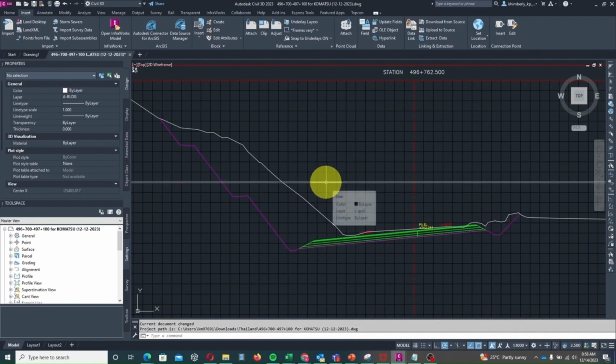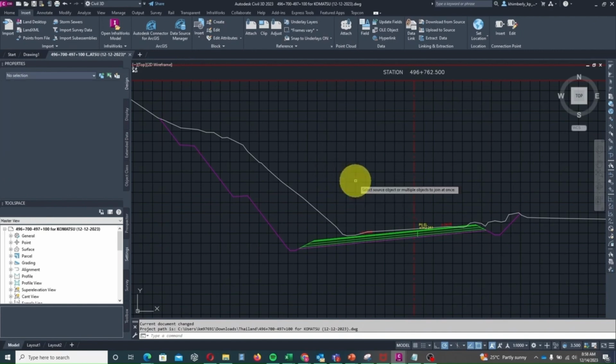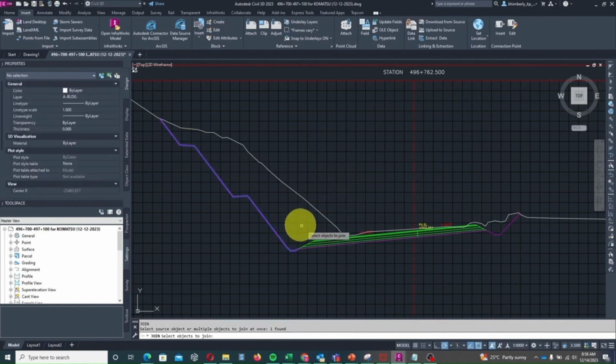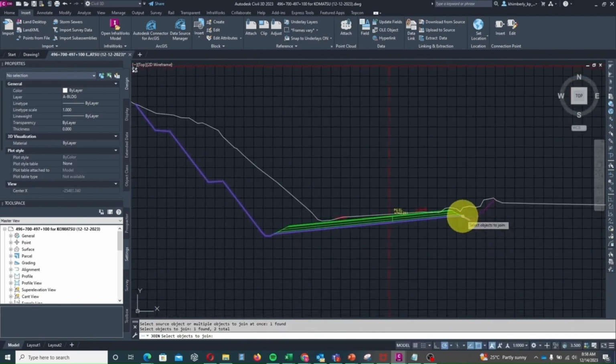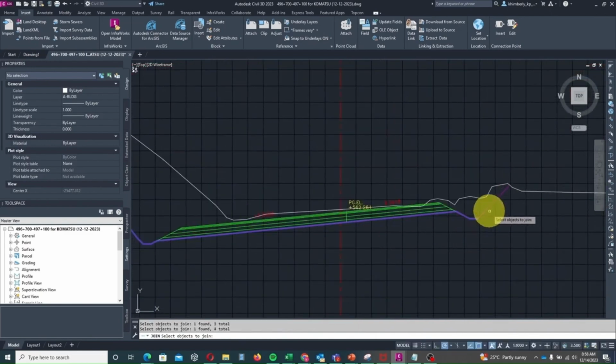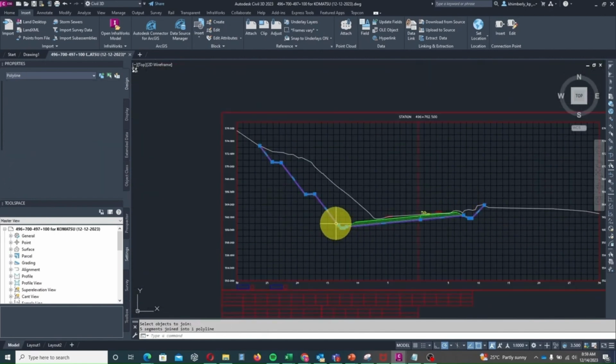Right now, pink lines are separated polylines. So before converting it to block reference, let's combine it to become one polyline. To do so, use join command. Then click all the pink polylines to be joined. And then press enter. Polylines has been successfully joined.